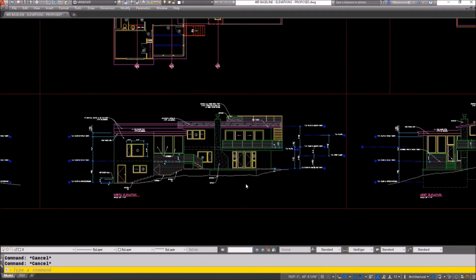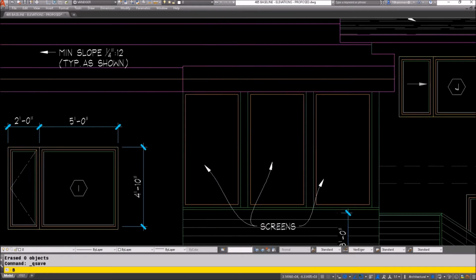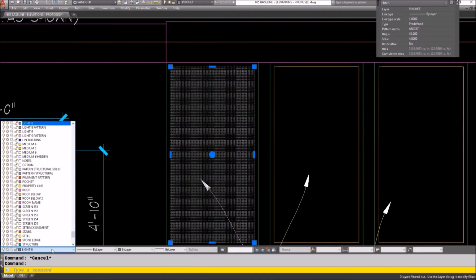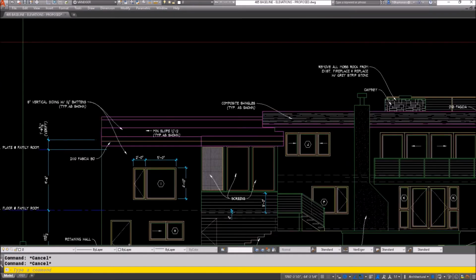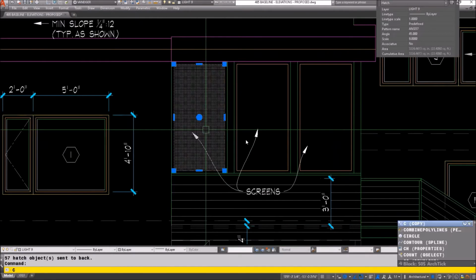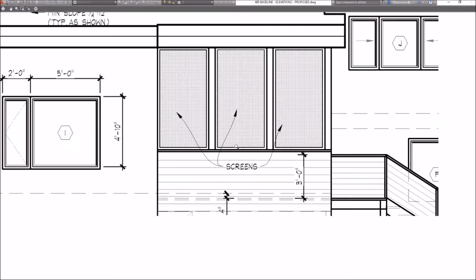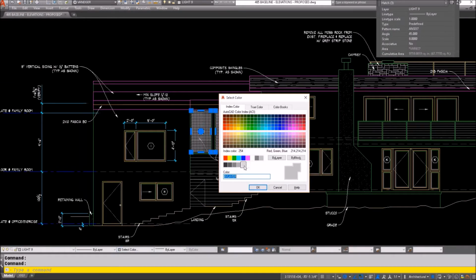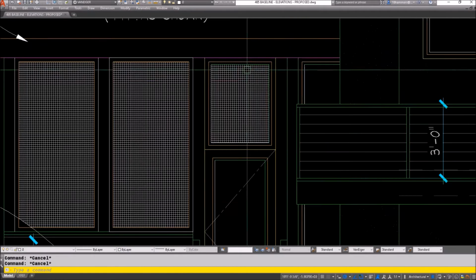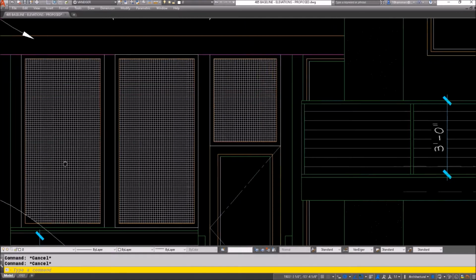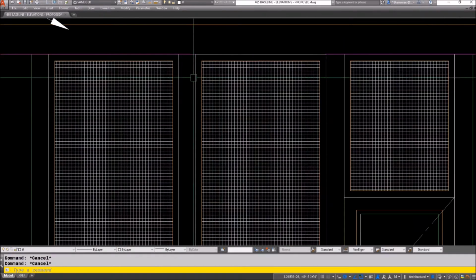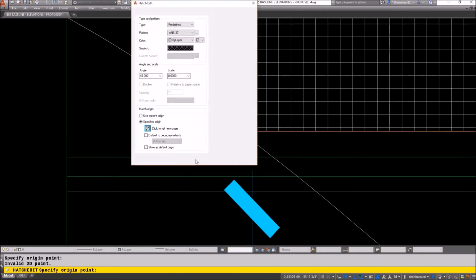This turned out to be doors. I didn't realize it was sliding doors. It wasn't sliding doors, so I had to go back into, I'll show you that in a minute. This is that screen I was talking about. I used shade 9, which I had set to like, I think 80% fade or 20% fade, it's either way. And there it goes, 9. So that fits in there. This is the screen porch. This is the other side of the screen porch. Over here I messed up. See, I'm using the control key to eliminate those vertices on that hatch.